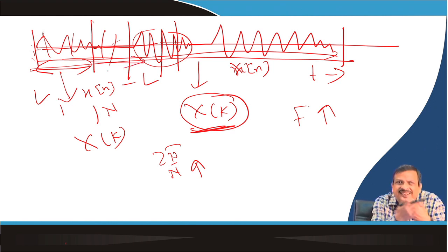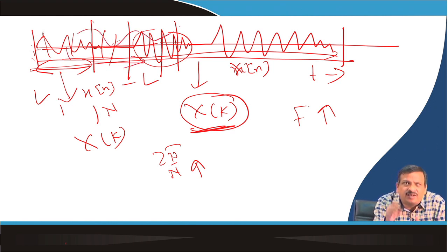I am not getting how the signal changes along the timeline. Time resolution increase means a small portion of the signal and the length of the DFT is less. Time resolution decrease means a large portion of the signal I can take. So, if I increase the time resolution, the frequency resolution decreases. If I increase the frequency resolution, the time resolution decreases.